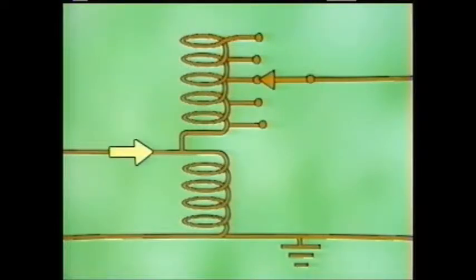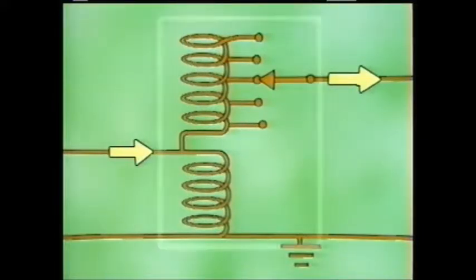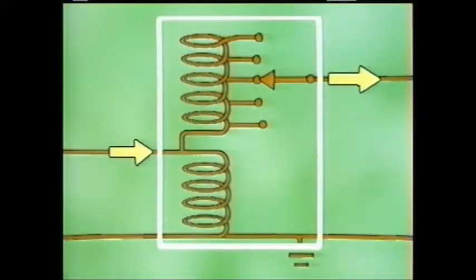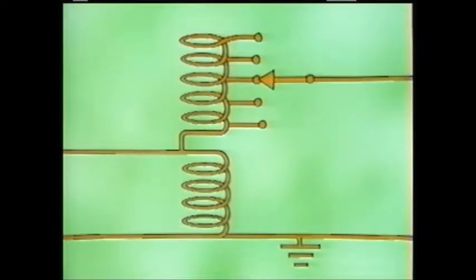The voltage supplied to and tapped off voltage regulators is primary distribution voltage. All a regulator does is adjust the voltage within a specified range of values in order to correct for drops in voltage caused by changes in load demand and characteristics of distribution lines. Now that you have a basic understanding of what a voltage regulator does, let's see what one looks like in a distribution system.